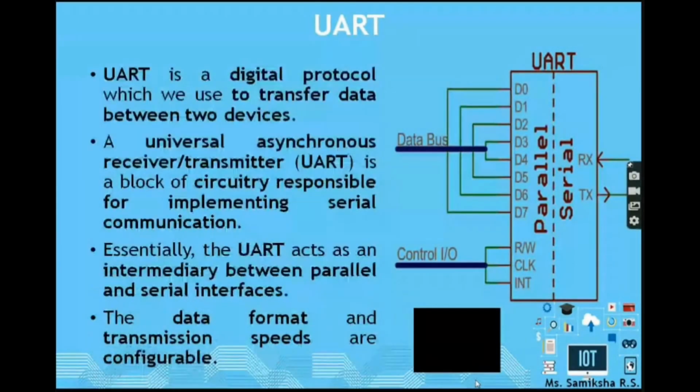So as I told you, I'll be sharing the concept about UART. So what is UART? UART is a digital protocol which helps to have seamless data transfer between two devices. Devices can be of different types, they can be parallel or serial. If they are parallel, they send 8 bits at one time simultaneously. But if they are serial, they send single bits one after another in a series.